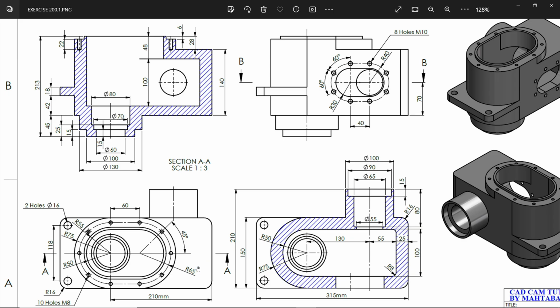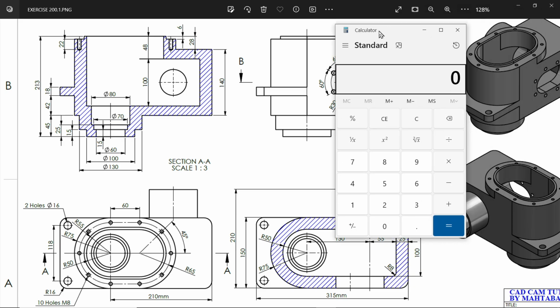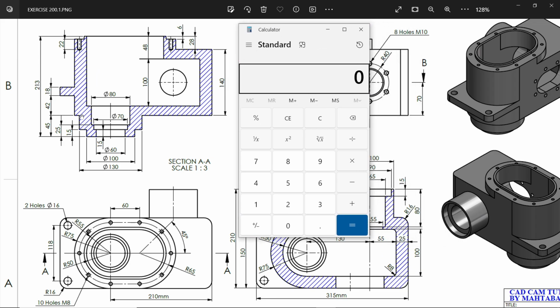And this side rectangular body is 140 millimeter, 28 millimeter below this section. So first we will create this body, and this is going up to, let's calculate now, up to here. Now look, this is the total, you will observe from here 140 plus 28, 168, up to 168. Then after 28 millimeter, 140 millimeter, this rectangular body, and then there is one flange, like 18 millimeter, and how